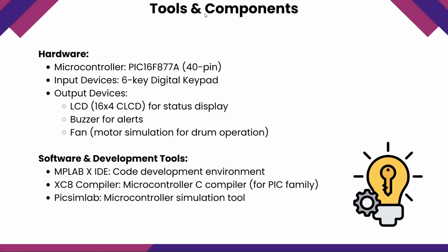Let's discuss the tools and components that I used for this project. The hardware components. First, I used a PIC16F877A microcontroller. This is a 40-pin microcontroller. The input device that I used is only a 6-key digital keypad. The output devices that I used include, first, a 16x4 CLCD display for status display. Second, a buzzer which I use for alerts. And third is a fan which acts as a simulation of the motor for drum operation.